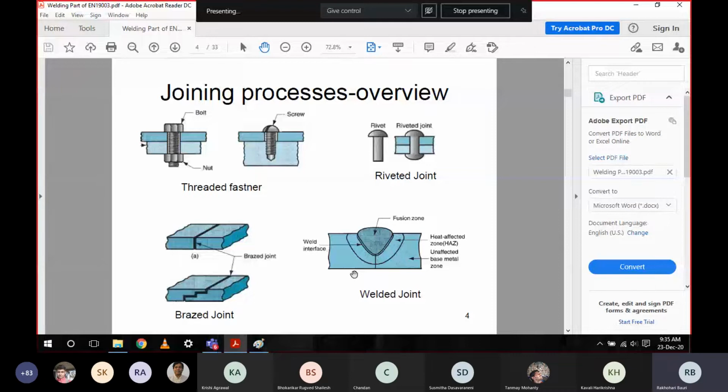You can understand it like this: if grains are smaller, then there is more adhesion between them, or they get more interfaces for bonding. So they increase the strength as compared to larger size grains.